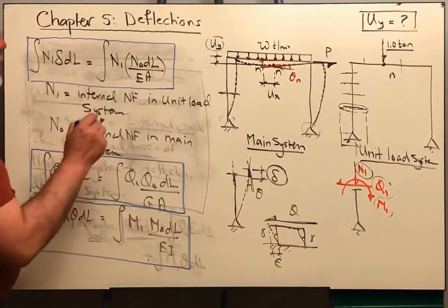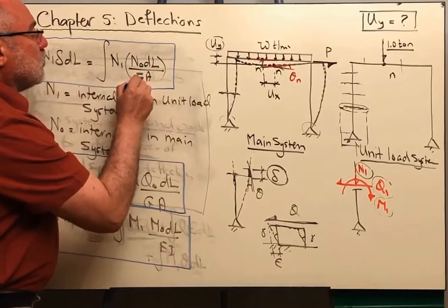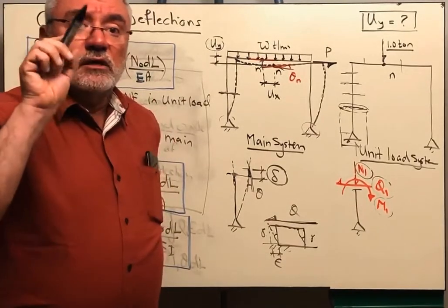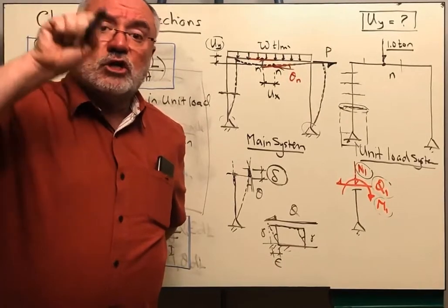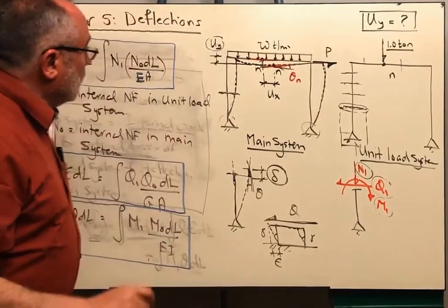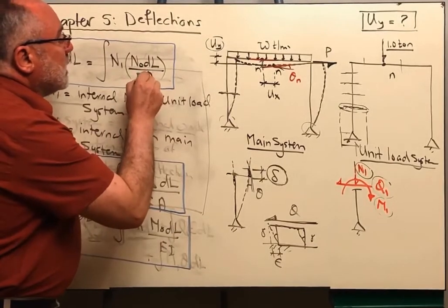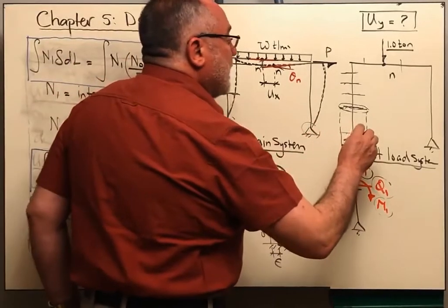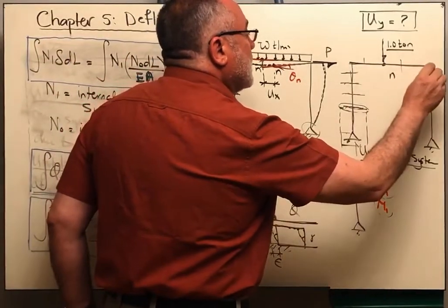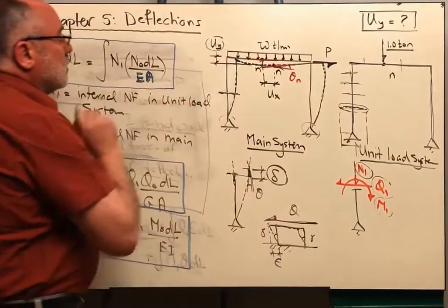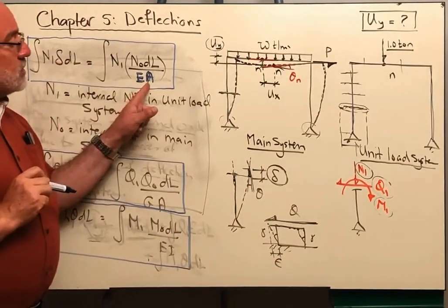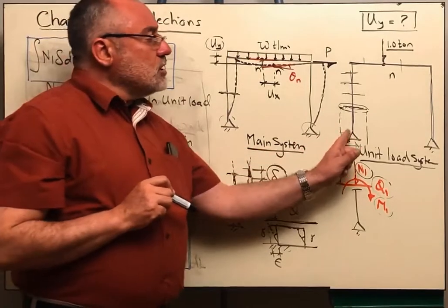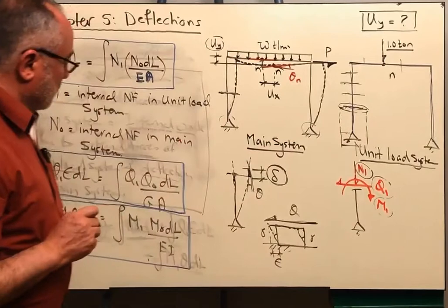Take care. What is E? It is the Young's modulus of the material, which is the slope of the tangent to the initial portion of the stress strain curve. What is A? It is the cross-sectional area of the beam. For example, if the element here has the same cross-sectional area, then this will be the value of A. If the value of A is changing, it will be considered as a term inside the integral. It will be changing with the length of the frame itself.